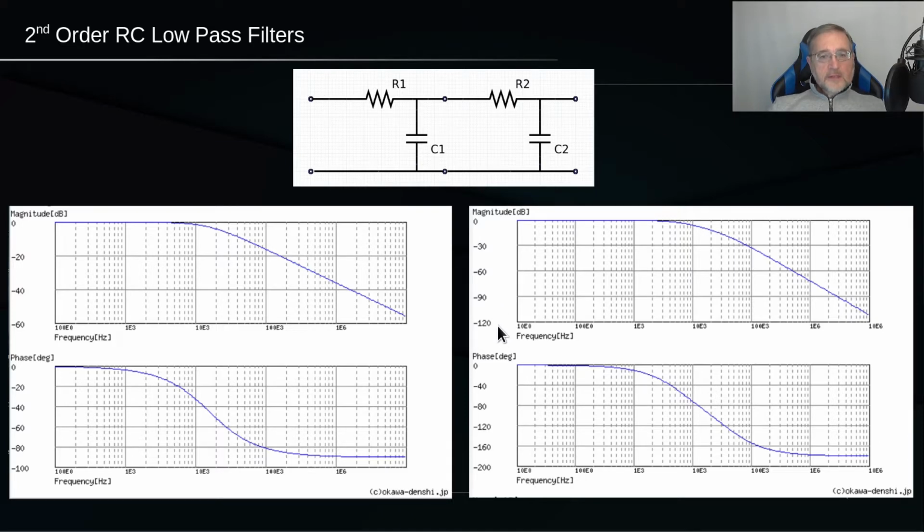And that confirms that the attenuation of the two first-order filters in series that make the second-order filter adds up and therefore doubles. And it is also true that the phase shift doubles, going from a maximum of 90 degrees to a whopping 180, according to these pictures. And that's exactly what we have seen in the lab experiment. But in the same lab experiment we measured a cutoff frequency definitely lower than the one of the first-order filter. Why this change, and why only this one?